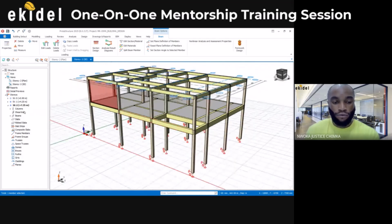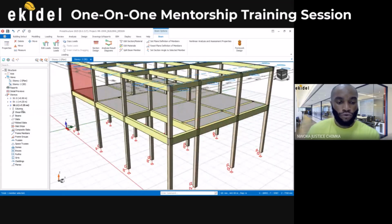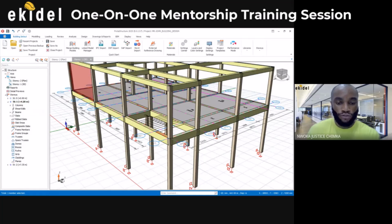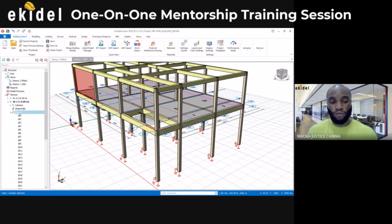So now we add the wall load generally to all the beams here on this floor. We can come back to story 1 where we have the load, which is this level. Then click on your beam here, drop it down by clicking on this arrow here, or just double click on this beam. You just drop it down.